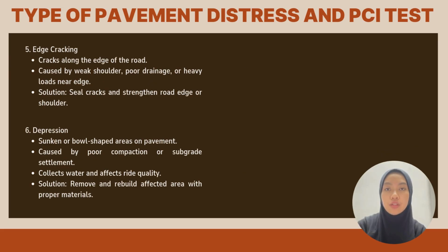Okay, so next is edge cracking. These are cracks along the road edge. They are caused by a weak shoulder, bad drainage, or heavy load. We fix it by sealing the cracks and strengthening the edge.